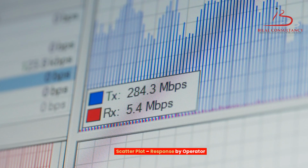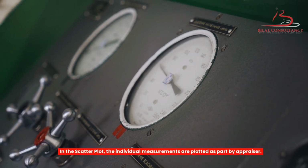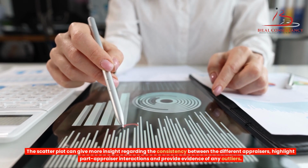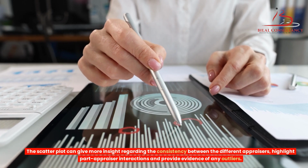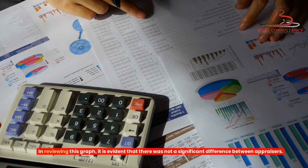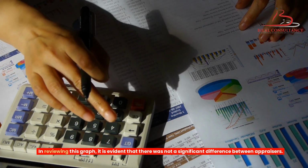Scatter plot, response by operator. In the scatter plot, the individual measurements are plotted as part by appraiser. The scatter plot can give more insight regarding the consistency between the different appraisers, highlight part appraiser interactions and provide evidence of any outliers. In reviewing this graph, it is evident that there was not a significant difference between appraisers.